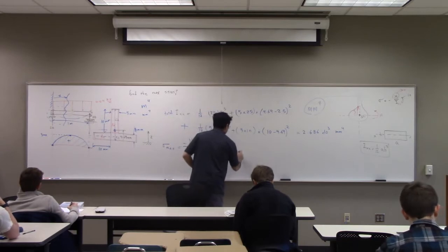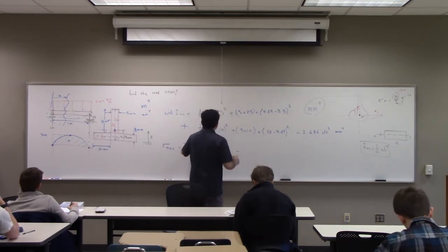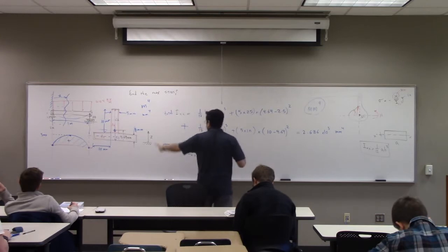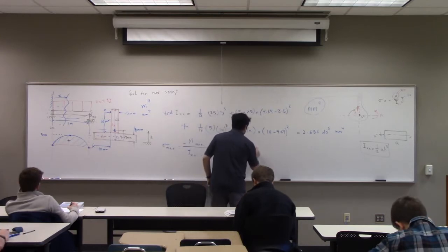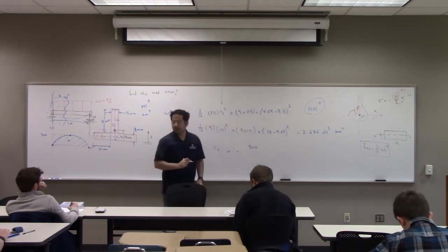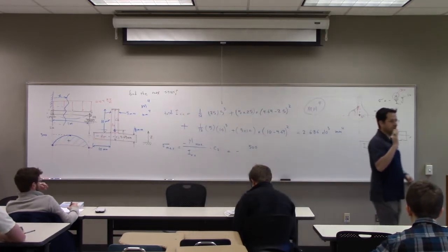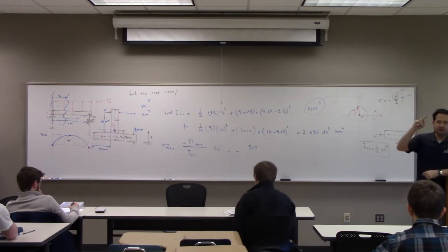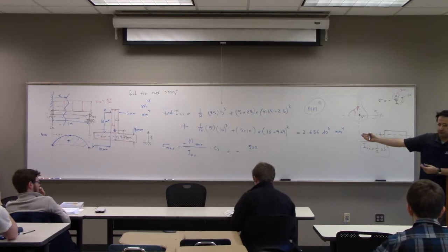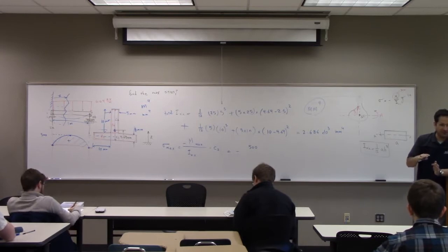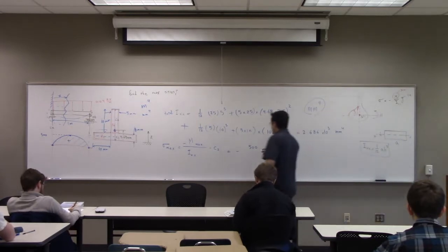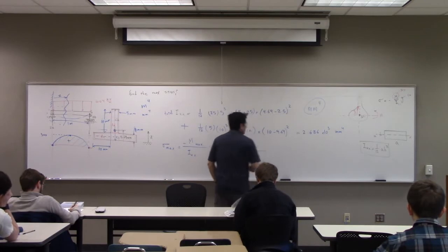So I say it's equal to negative maximum moment, which was 500 times, you see, moment should be what? Newton meter. I have 1 over 2k, half of k. Half of k is just 500, that's enough. If you have 2k, then you say 2 times 10 to the 3. This stuff is easy to miss. All right, so I have negative 500 divided by Ixx.